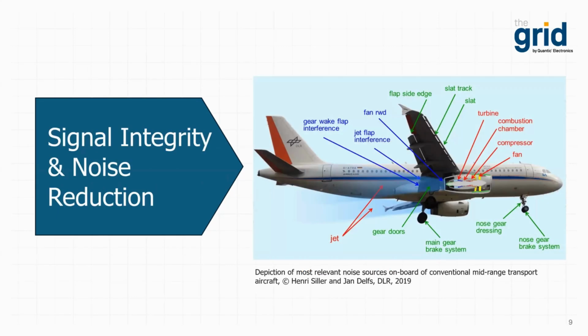To optimize signal integrity and noise reduction, capacitors are used for input-output matching and coupling in RF circuits, maximizing power transfer and minimizing signal reflections. Capacitors act as DC blocking components, allowing only AC signals to pass between circuit stages. This is essential for proper signal processing in avionics. They suppress electromagnetic interference, which is critical in the electrically noisy environments of an aircraft.